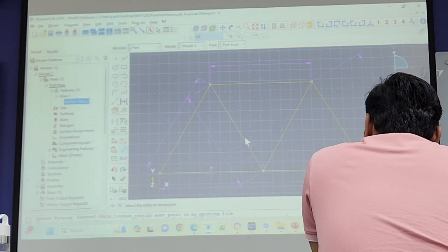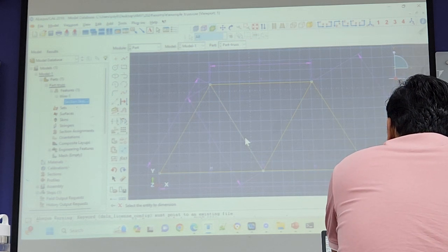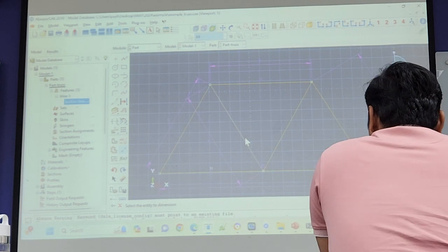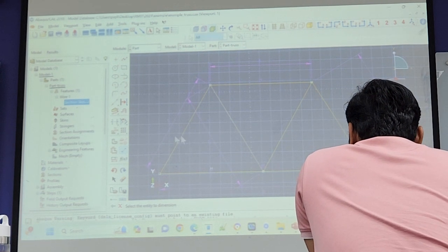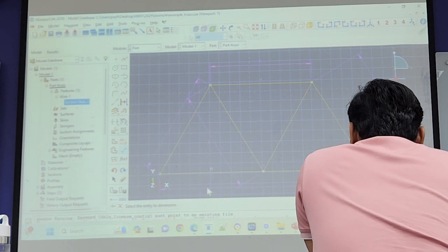Remember just now when I hadn't added the 1 meter line, it doesn't go into a trapezoidal shape. It goes to a few types of shape. Once I add the 1 meter line, it straight away constrains it. It automatically generates this shape to fit my provided constraint. If I over constrain this, I say 1 meter, 1 meter, 1 meter, then it doesn't allow Abaqus to generate anything. Then it becomes a magenta line, and you cannot escape from this. You cannot generate a sketch.